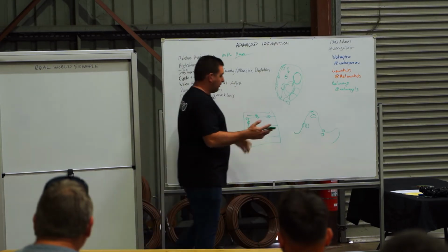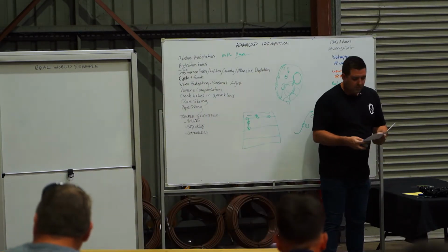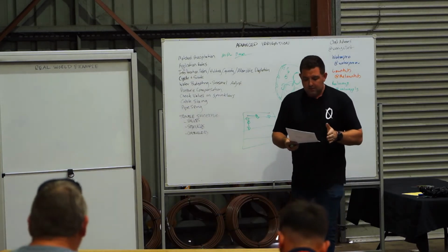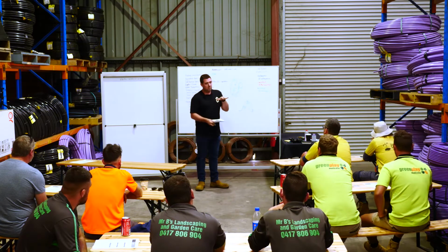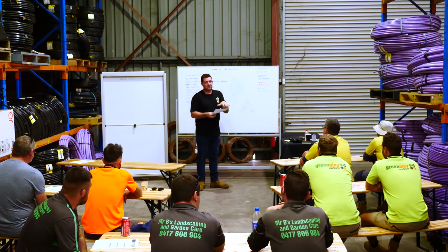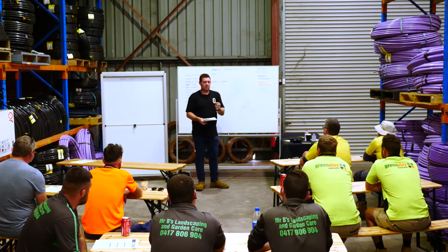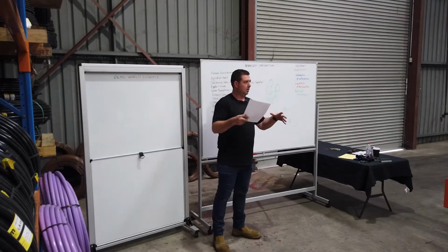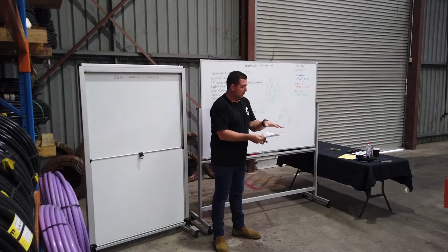So you'll have your soil type. For this situation, we've got a clay loam that can take 5 to 10 mil an hour. The holding capacity of that soil might be, say, 6 to 10 mil total. So obviously you can't physically get any more water in there. If you look at a clay particle versus a sand particle, the sand is just going to go straight through and keep going, whereas the clay might hold it.